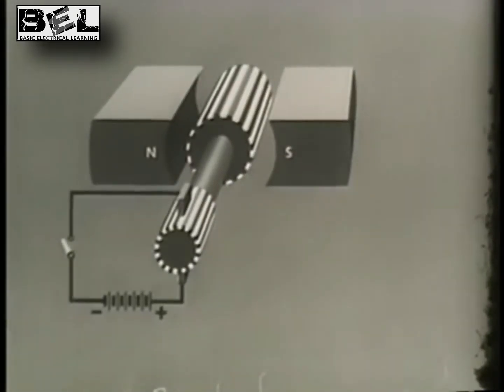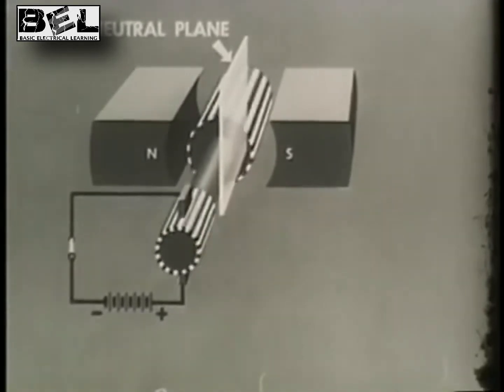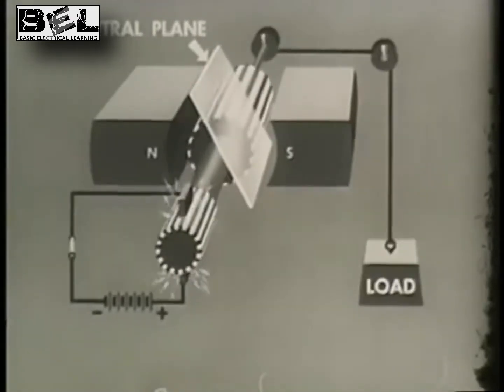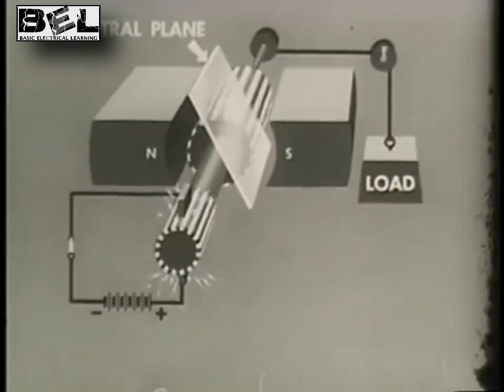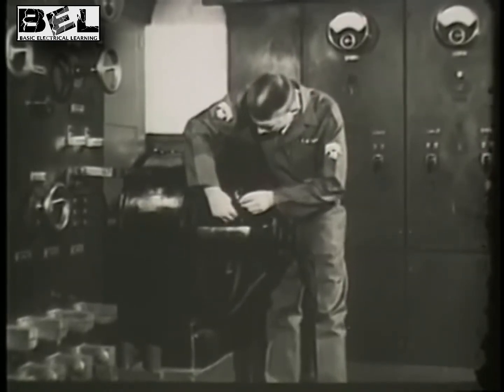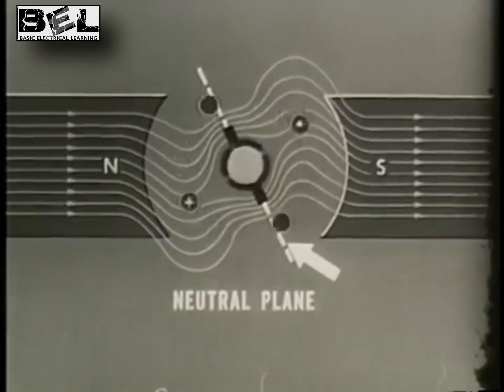Here in the motor, as in the DC generator, there is a neutral plane. The interaction of the conductor fields on the main field causes this neutral plane to shift and sparking to occur when a load is added. Sparking in DC motors also produces burned commutators and interference in nearby electronic equipment. This sparking can be prevented in one of two ways. One is by the adjustment of the brush position. The brushes are moved until they lie in the adjusted neutral plane.